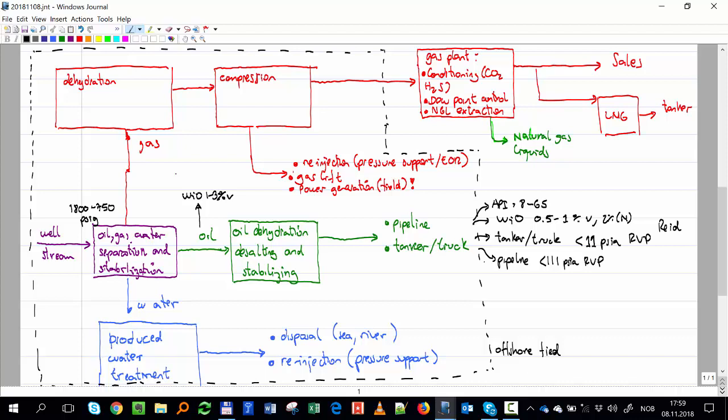The salt content also you have to control, that's why we sometimes need to dissolve. Salt causes corrosion, and also mineral accumulation. So the salt content has to be something between 10 and 30, and this is pounds per 1,000 barrels. So here you see we have a mess of units, but I guess you are happy. You are seeing some field units for the first time in the course.